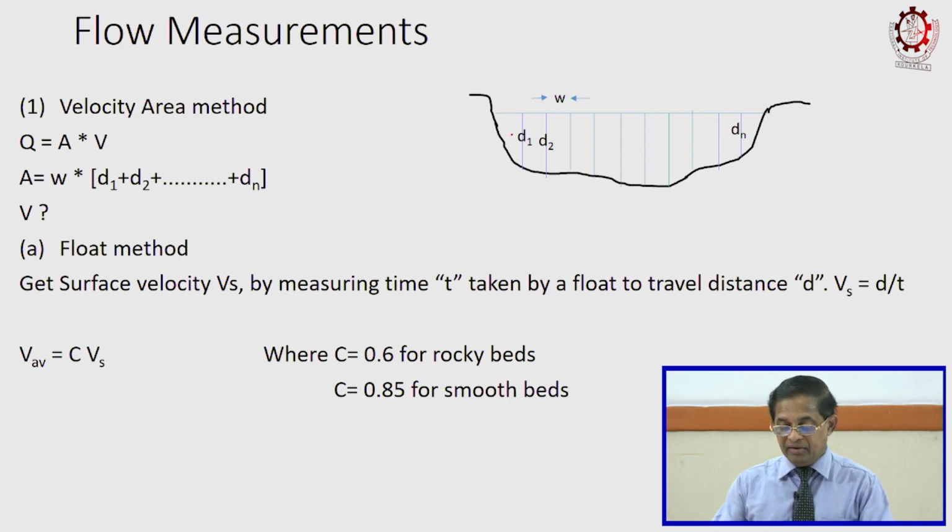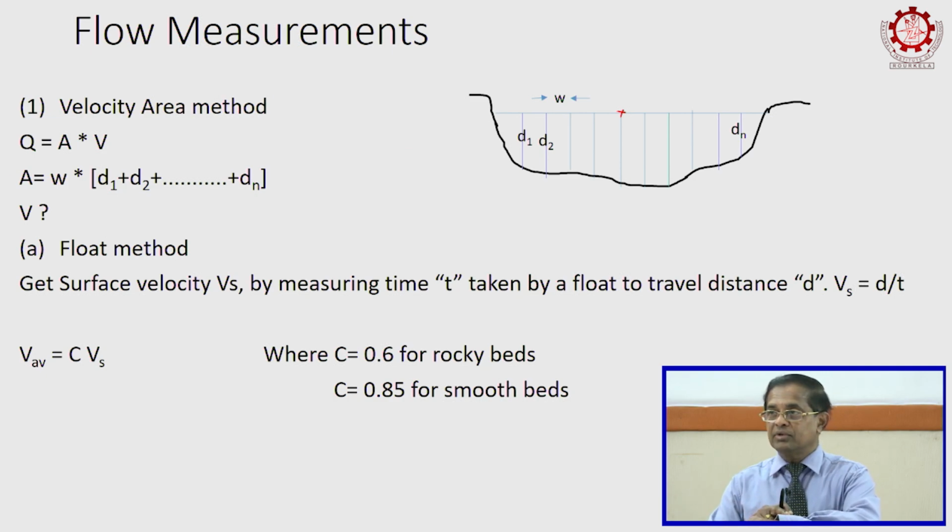Then you can measure the surface water speed. You can put in something to float, and measure the time taken to go a certain distance. But you can measure only the surface speed; the speed will not be uniform, so you can't measure the average speed directly. Take your watch, note the distance it has gone in 1 minute, and then you know the surface speed.